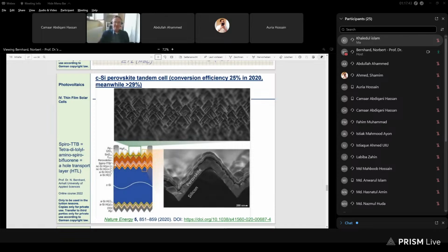And from top to bottom, the band gap is decreasing, and every part of this quadruple cell is using a different part of the electromagnetic spectrum. And these cells can be very highly efficient under concentration. We can have efficiencies of more than 40% or almost 50%. And you also remember from the second unit that in principle, we can approach by these concepts even higher efficiencies.